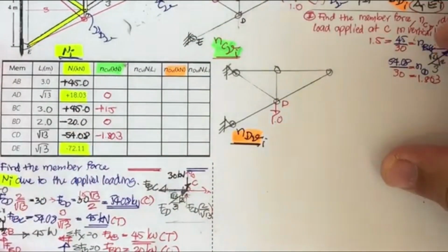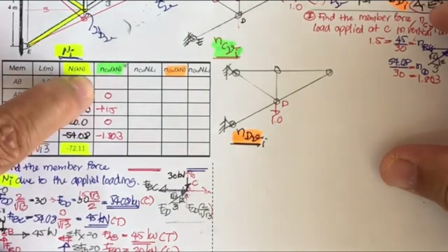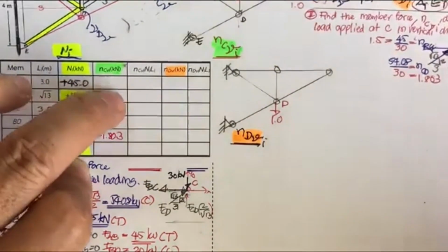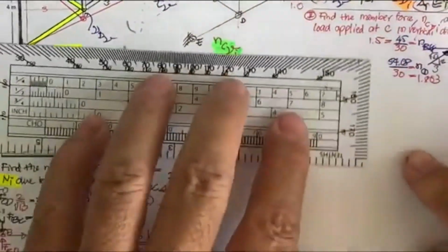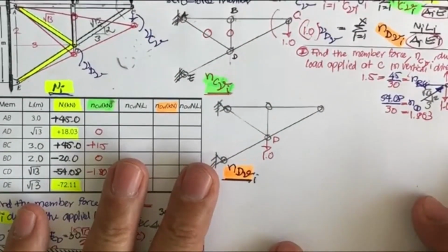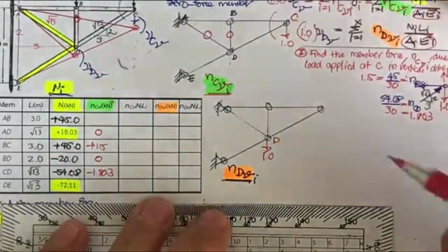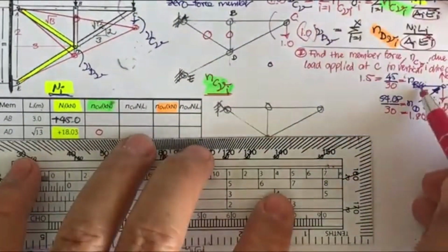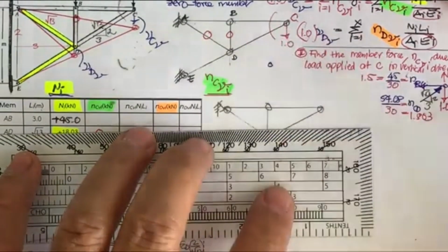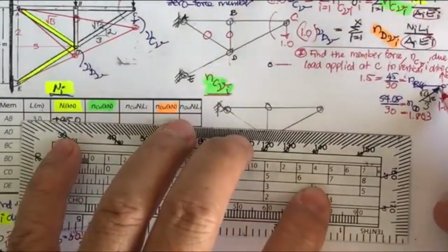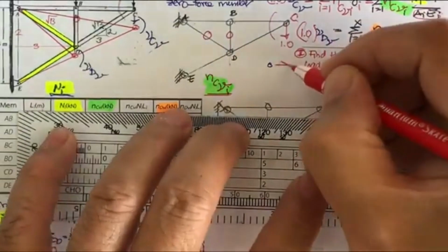So we have 2 elements to determine, the AB and the DE. Okay, say if you push the point D, and then you try to again move and consider the point D, and the point D is here, and point D is subjected to this force of CB, so this is going to be 1.5, in tension.